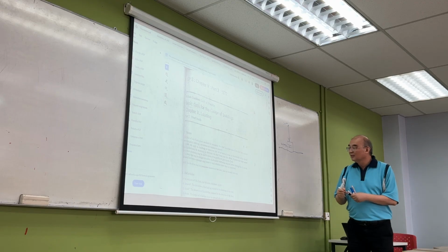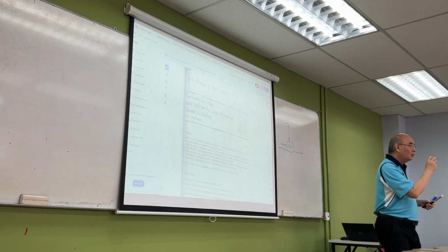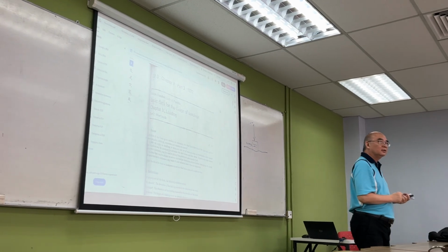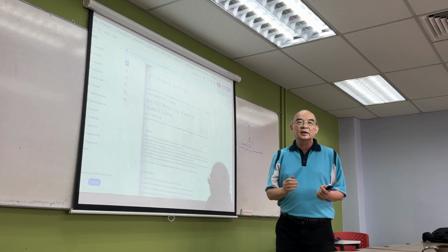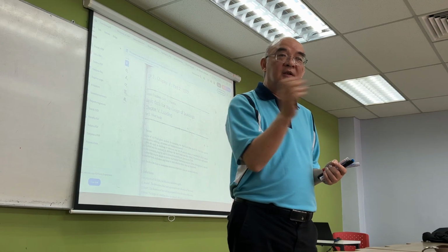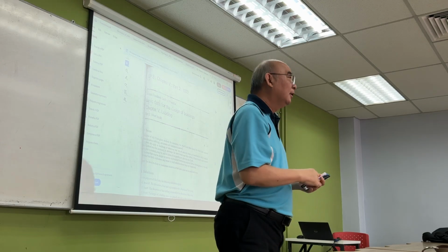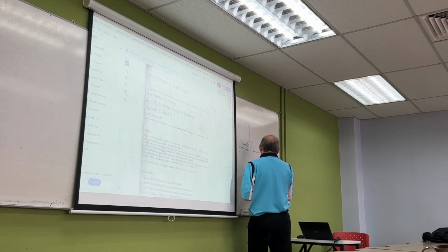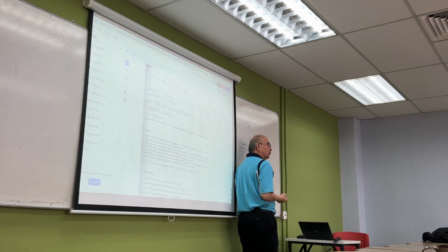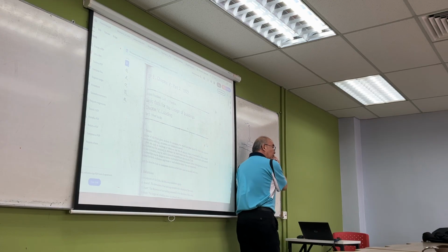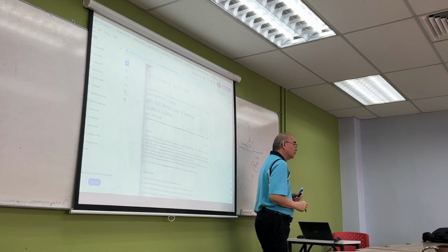The wind also has what we call a gust. What do you mean by gust? Gust is when sometimes the wind is suddenly strong. So this is a sudden gust. Now when you take an average, let's say the average is 50, the maximum could be 100 and the minimum 0. If you design for 50, what happens if this 100 comes?